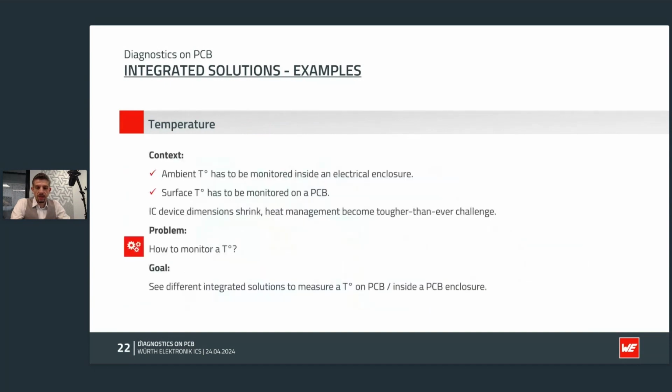The context of the temperature measurement is as well a little bit peculiar, as the temperature sensor is giving out its own temperature, not the ambient temperature. The position of the sensor makes a huge difference depending on if you want to know the inside temperature of an enclosure or a track temperature on a PCB. For this purpose, we are offering new temperature simulation services to our customers to allow a better design from the start.